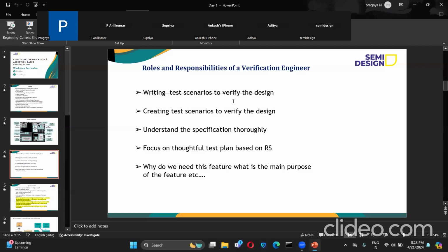So we have something called a verification plan in the industry, which everyone uses, where they extract all the features of the design in a particular manner. In the verification plan, they give the different features, the purpose of each feature, and the entire scenario, meaning how you are going to generate the stimulus. For example, first you create some body for it. In that body, what are the different steps you will write? First you create the stimulus, then you randomize it, like that.